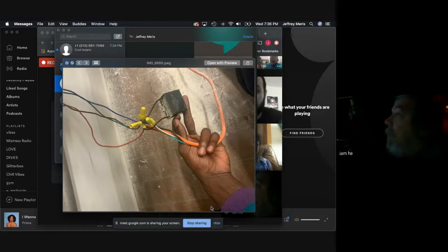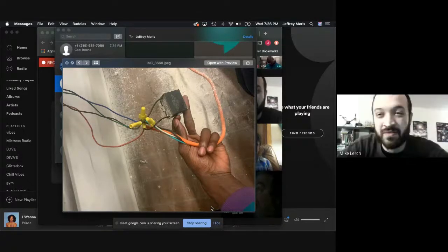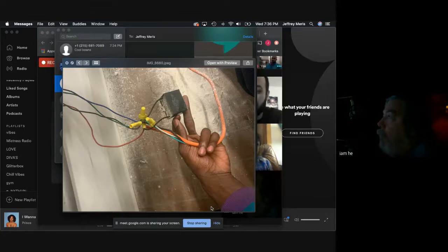You could use a mechanical relay, but at that point it's either on or off. But with a Triac, brightness can change. A solid state switch allows you to do something in between rather than discrete on or off. Yeah, a Triac will control AC current. A small amount of AC current coming in will control a large amount, a higher voltage AC current going out. It's the same thing. You can think of it as a transistor, only it works with alternating current, where transistors operate with direct current, DC. So think of it that way.